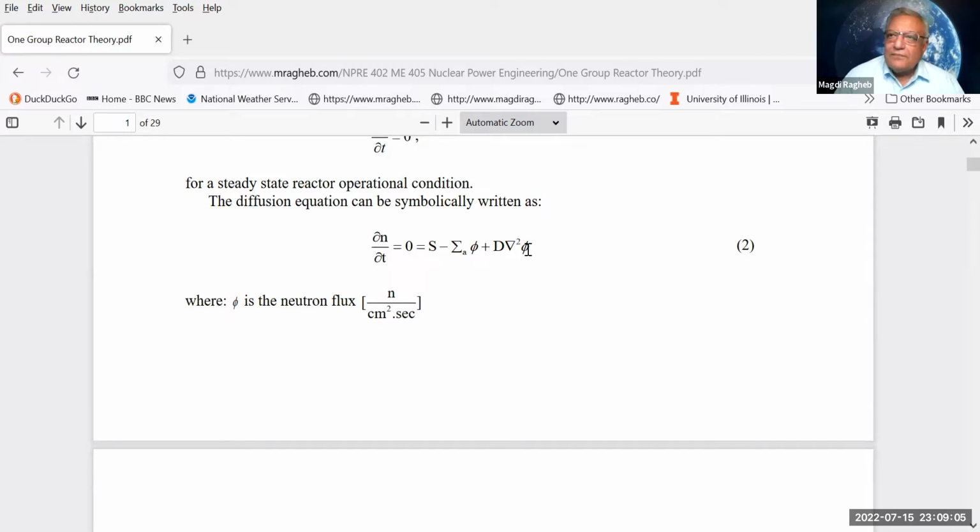I gave you a problem along this line. When you deal with the flux, it adds up in a scalar way. When you take its derivative, the gradient of the flux in Fick's law, it becomes a vectorial quantity. The same way that if you take the gradient of the temperature, you get the heat flux, a vectorial quantity.